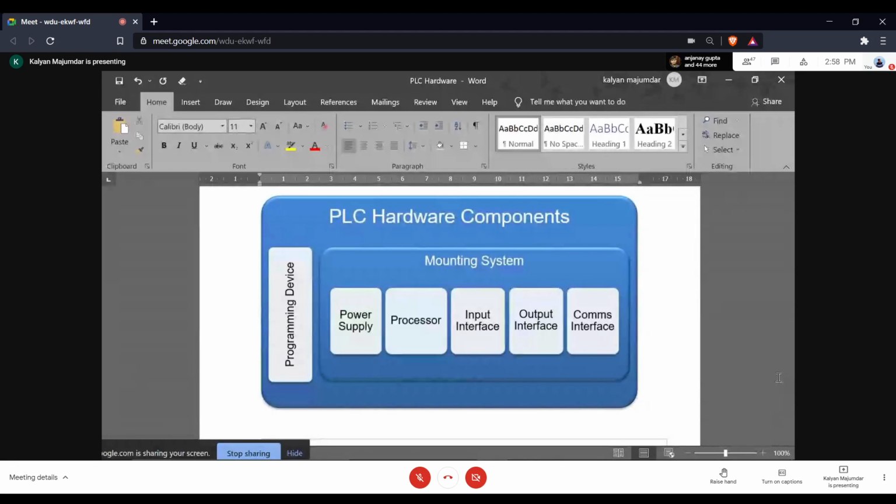and when the PLC is executing the program, for example, after going online you press run, that is, you command the PLC to run the user program, and then you can see the status of the program in real time. So again, there's communication. The program, remember, is being run on the PLC hardware, and that real-time status is being transferred by the communication link to your courses environment, where you can see the logic being executed in real time. You can debug if you have any problems.